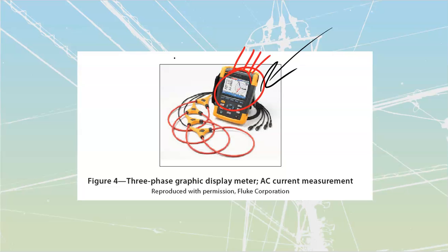Power loggers are generally going to be used for things like: I'm going to add on to a service, so I've got to figure out how much room I have, or can I actually add this expansion to the plant, where we're looking for just coarse data. If we need to catch what the culprit is, you're going to have to go with the power quality recorder, which is going to give you fine detail inside of there.